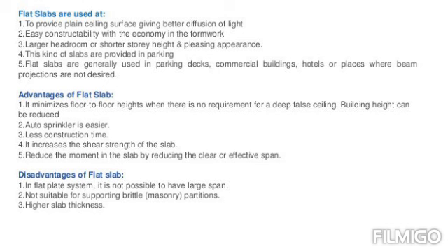What are the disadvantages of the flat slab? Number 1, in flat plate system, it is not possible to have a larger span. Number 2, not suitable for supporting brittle partitions. Number 3, higher slab thickness.